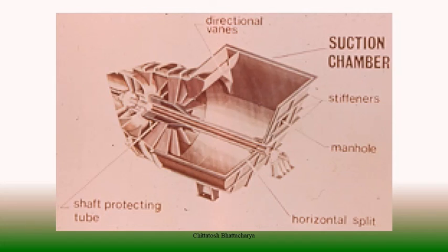And in fact, whether we operate the inlet guide vanes or inlet dampers, the flow restriction is from 30% to 70%. Beyond 70%, the flow is 100%.